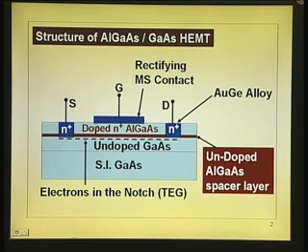And on the top of this, you have got a metal semiconductor contact, which is a Schottky barrier, which is the gate region. So, just like in the case of MESFET, you have got the source and the drain, both as in the case of MESFET and MOSFET. You have got the gate. In the case of MESFET, you have a doped region between the gate and the substrate. In the case of MOSFET, you have an insulating layer between the metal and the substrate, that is the MOS.